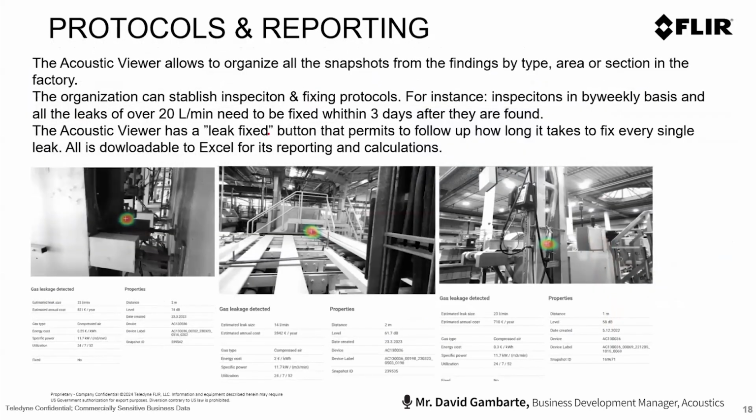So now talking about leaks, right? The acoustic viewer allows you to organize all the snapshots from the findings by type, area, or section, as we have been mentioning already. The organization can establish inspection and fixing protocols. For instance, if you decide that we will do inspections on a weekly or bi-weekly basis in our factory, imagine you say, okay, we will do an inspection every week.